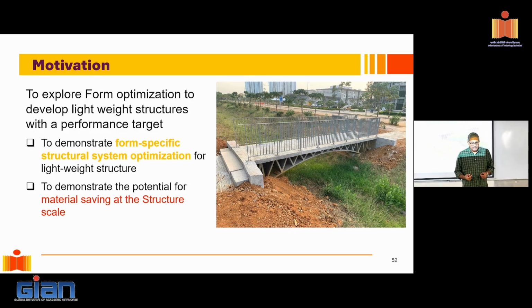For me, the measure is, if I calculate the difference in stress between the highly stressed point and the lowest stress point, if that difference is large, that means it's a very inefficient design. An efficient design would be if I'm able to reduce that difference, and the most efficient design would be when there's no difference between the highest and the lowest stress material.